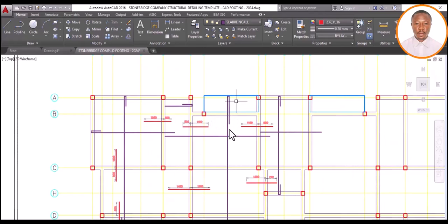Now, if you look at this, it's not going to be applied. We cannot apply it here because there's a principle that says that the length of your cantilever is multiplied by 1.5, which means whatever your result is, that is what is going to enter into your slab in order to withstand the force of this cantilever. And you know that when it comes to cantilever, we reinforce the top, isn't it? Because the tension is on the top, and you know that